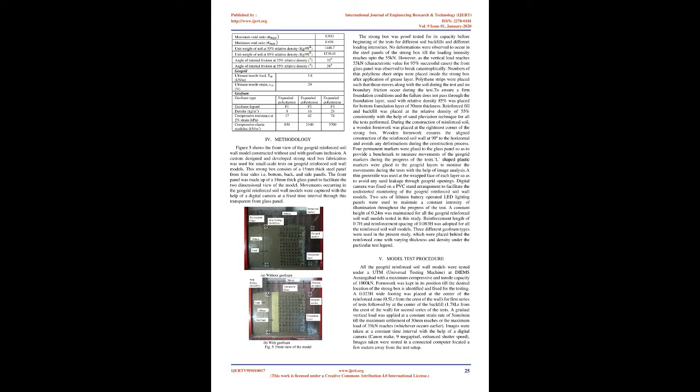3. Model material. A. Sand. The sand used for this study was Bombay Beach sand, composed of rounded and sub-rounded particles. Sand was classified as silty sand, SM, in the Unified Soil Classification System, USCS. The model sand was found to have internal frictional resistance of 32 degrees, 35 degrees, and 38 degrees for 55%, 75% and 85% relative density respectively. Table 1 summarizes the properties of the model sand used in the present study. Figure 2a shows the photographic view of the model sand.